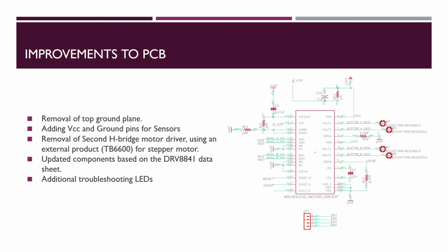The H-bridge driver that we did leave on the board needed additional resistors added for current sensing to determine how much current to output to each of the motors it controls. This was missing in our original design, but was documented in the datasheet. The last thing we added was additional LEDs to the output pins of the microcontroller for troubleshooting and determining that our logic is working correctly.